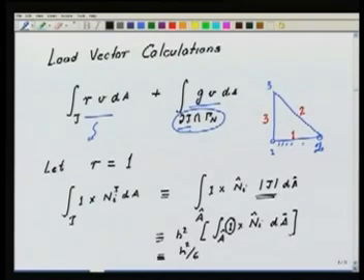Let's go back. If instead of this constant R I had R as some function of x and y, then I have to map this as a function of psi and eta, as R hat of psi and eta. So this integral now has to be done piecewise, that is, for each of the shape functions I have to find the integral. I cannot say now that the load vector term coming out of this integral is the same for each of these shape functions. This is one thing you should keep in mind. I have to do the explicit integration there. Fine, so I have this coming out of the f R tau.